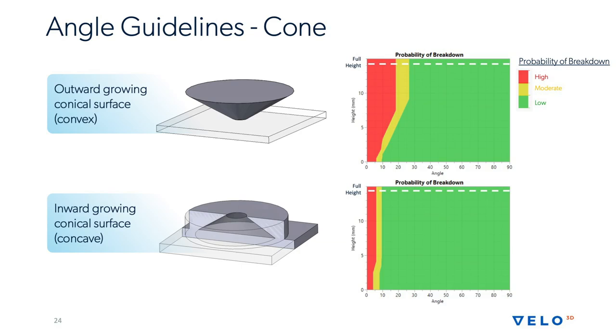On top of that, you have a secondary low angle surface here, or skin surface, that's being applied. That's basically melting a ring, solidifying, and it's warping with a similar vector, that being, it's warping kind of in and up. And those two stress vectors work together to make a leading edge that really wants to warp up. And so your minimum angle that you can print safely is higher in a lot of cases. It really depends on how long you propagate this, because the stress accumulates over many layers.